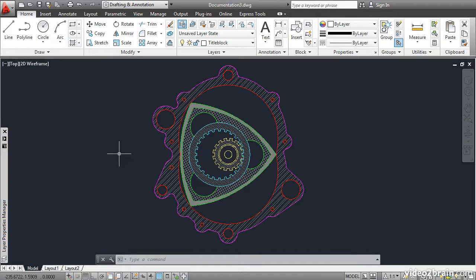Here you will create a new annotative text style that specifies a paper text height. Then you will create an annotative text object with representations at two different scales. You will then arrange these representations to be displayed in separate viewports. Finally, you will create annotative text in Paperspace.